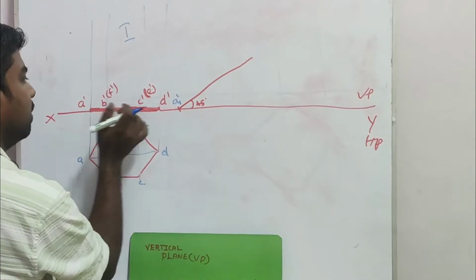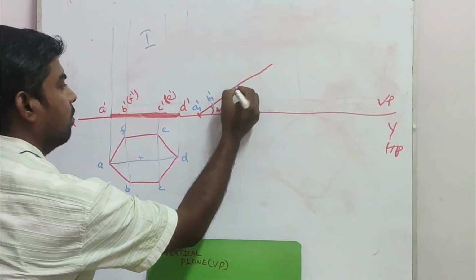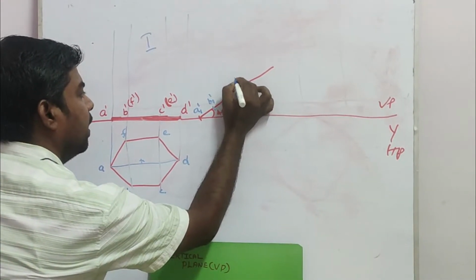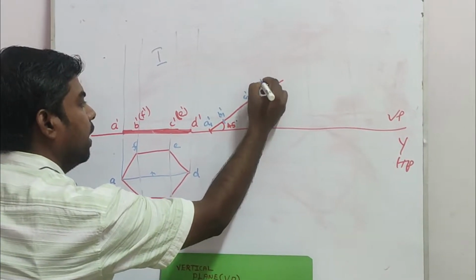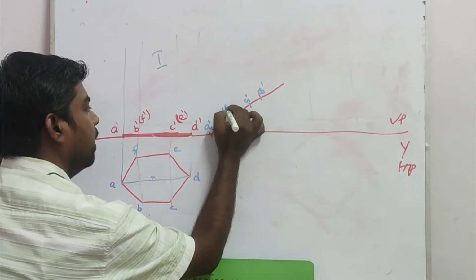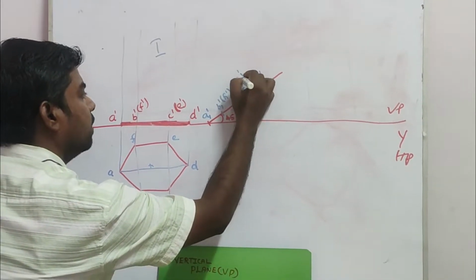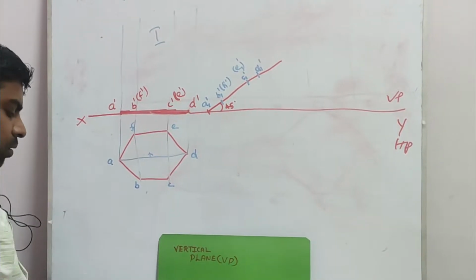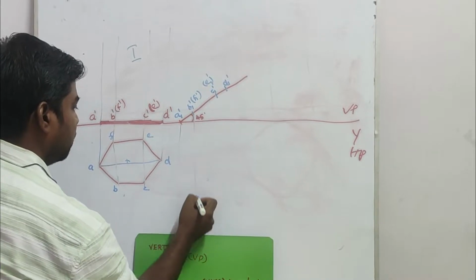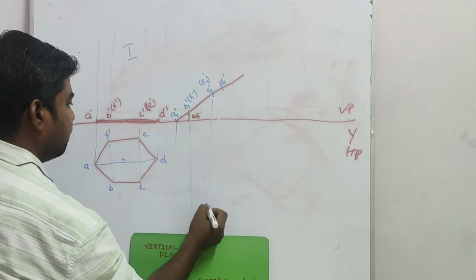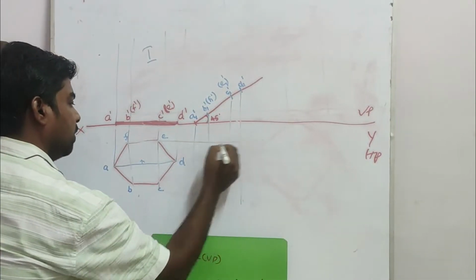After that you measure this distance and mark it B1 dash. Measure this distance, mark it, and that is C1 dash. This distance you mark, and that is D1 dash. So here it will be F1 dash, as well as E1 dash. Now as usual, we have to draw the supporting lines by using the 2H pencil, and then you have to draw the horizontal line from this side.